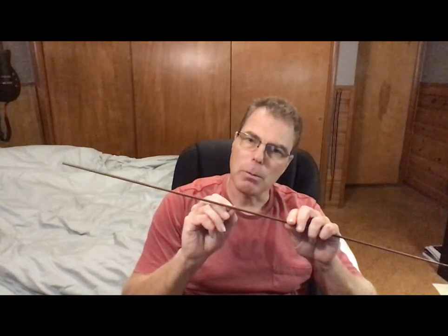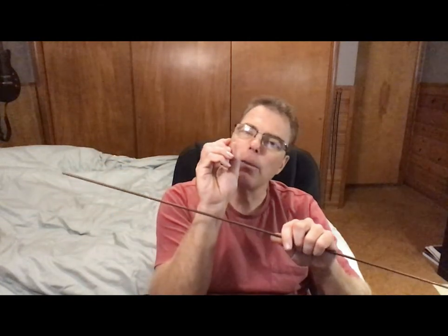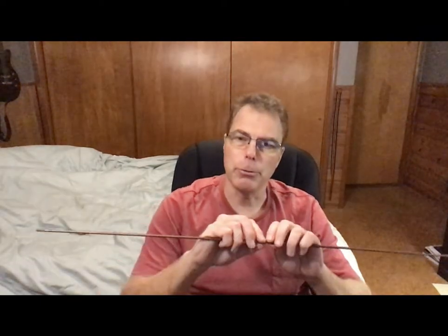The deal is, as I'm pulling on this, remember that the atoms are bonded together with kind of an atomic bond that's got a little electron cloud around it, but essentially, as I'm pulling on it, these atoms are getting slightly farther apart. And when I slice this way, you can imagine there's a lot more atoms, they're very small, a lot more of them across that cross-section than there are in the other 2. So you have more atomic bonds across this bar than you do in the other 2 bars. Therefore, it's going to take a lot more force in order to break it.